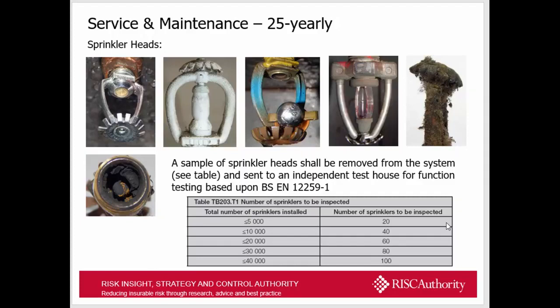The next picture along shows that the bulb is operated, but it hasn't actually shattered and allowed the valve seating to be removed, so that the water will not penetrate through the sprinkler head and hit the deflector plate and provide a spray pattern. It's just lodged in.